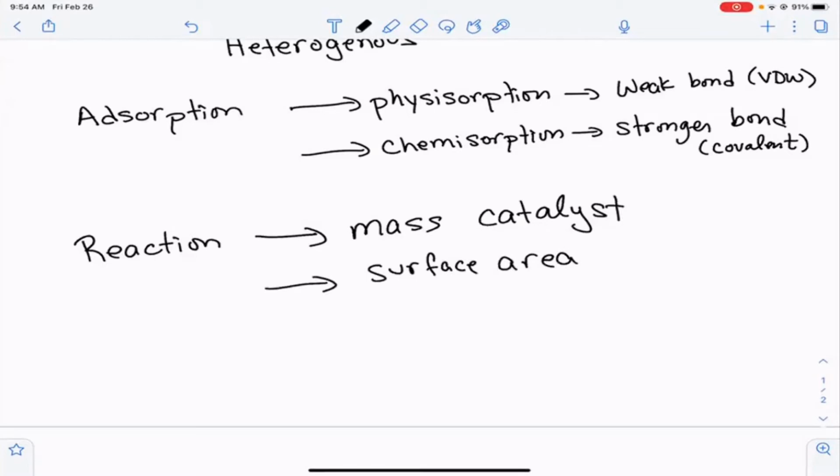And surface area is something that in a chemical reactor where you're implementing a catalyst, like in a packed bed reactor, we really try to balance increasing surface area with other things. And I'll talk about that in a second. But what we normally do is we try to increase the surface area generally.